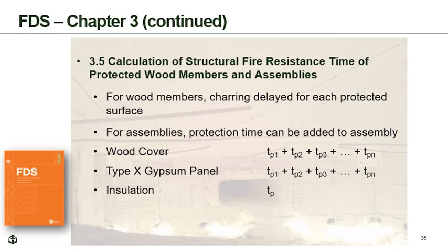These provisions for design of fire protection, both combustible and non-combustible protection, allow for designs that go beyond the 2-hour fire resistance rating limit that I mentioned a few minutes ago, which applies to the exposed wood member itself.